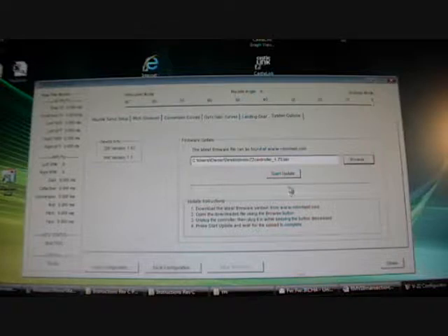So the way you load in the software is, I actually unplug the USB controller on the computer because it's easier to get to. I press the programming button on the controller and then re-plug in the USB and then let go of the button.